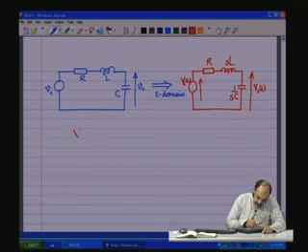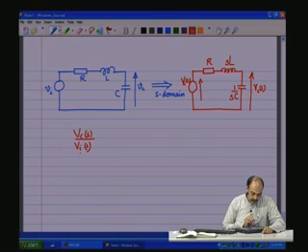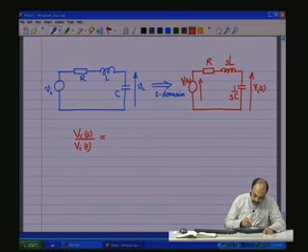So, to obtain, let us say, the input output relationship, that is the gain between the output and the input, which is Vc by Vi(S), the Laplace transform of the output Vc by the Laplace transform of the input Vi, which is going to give you the transfer function, which is here: Vi into 1 by S C divided by all the elements in series.